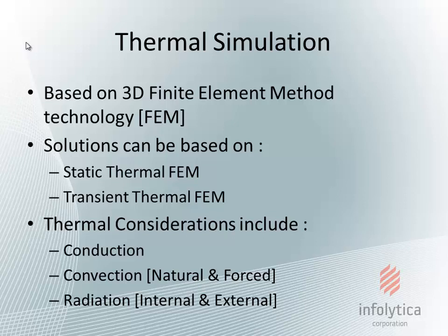Throughout the product, solutions can be based on either static thermal finite element methods or transient thermal finite element methods. In all cases, the thermal considerations include conduction, convection, both natural and forced, and radiation, both internal and external.